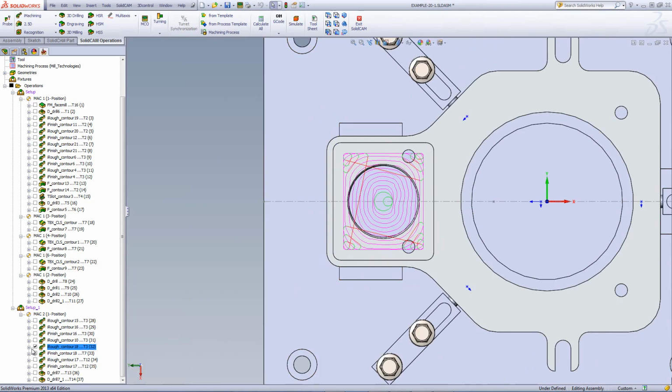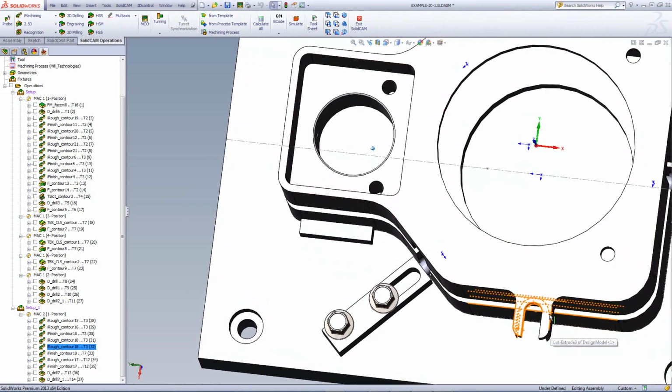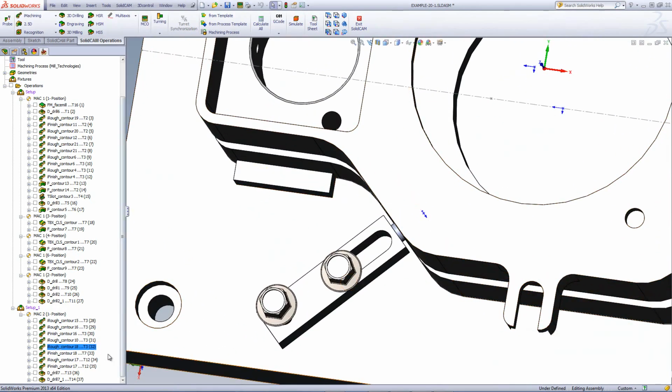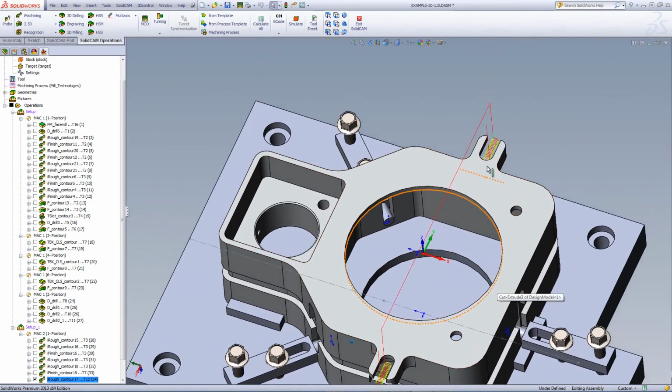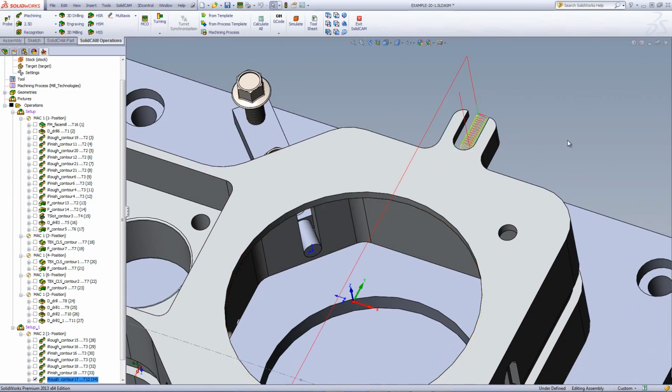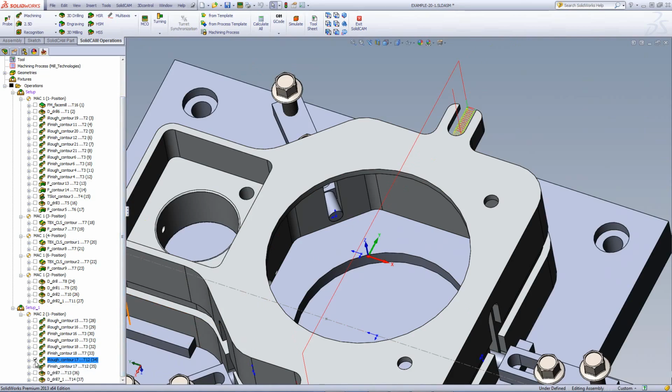Now, in addition to this iMachining operation that I needed for this pocket over here, we also still have these areas over here that I did not mill out yet. So for that, I've also used the option of iMachining, creating for this slot over here as well as for the slot on the other side, doing both a rough and finish operation for those slots as well.